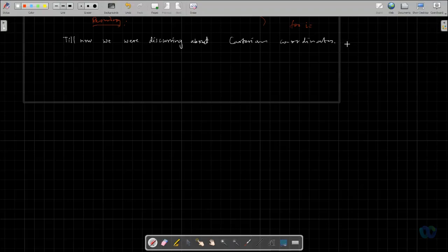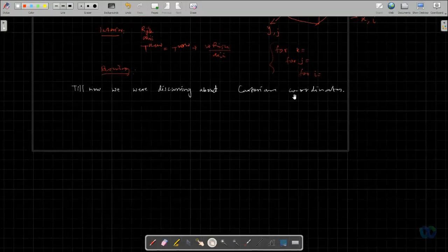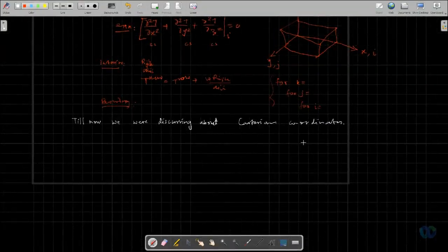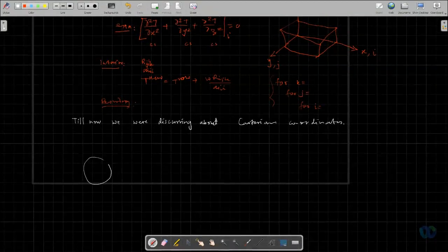Okay, in the finite difference method, some domain transformation is used. In the finite volume method, you need not solve the equations in Cartesian coordinates. Even if you have a cylindrical coordinate, for example, you need not, because you already have a discrete domain and this is a finite volume. Okay. And the volume can be of any type, so this is unstructured or any volume. So any volume can be dealt with, and if you calculate the areas and volumes properly, then you can simply use the Cartesian coordinate equations and solve the cylindrical or spherical coordinate problems.